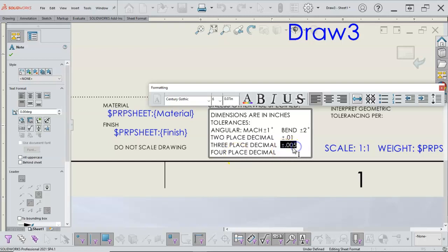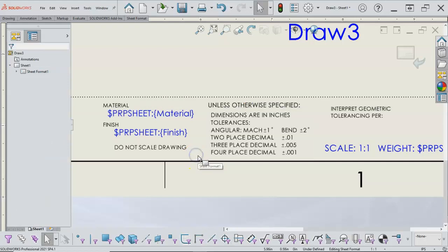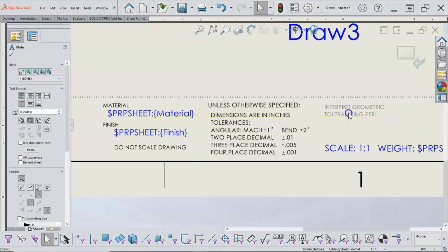And I'll just go ahead and copy and paste. So if I don't put some other notation on the print, I would say industry is probably half a thousandth, 0.0005. I tend to go plus or minus the thou to have control, but also open it up a little bit. If it's something that's really critical, plus or minus half a thou, plus or minus 2/10 of a thou, I'm going to assign that at the location with the dimension as a critical dimension.